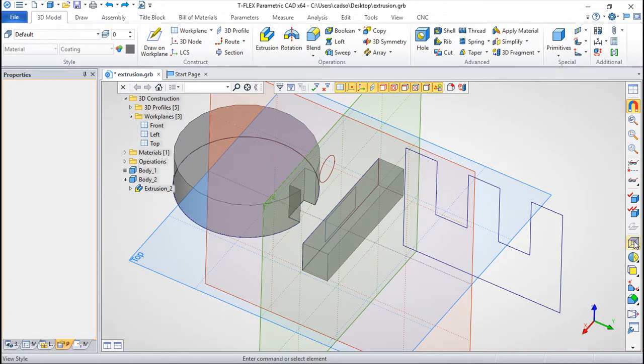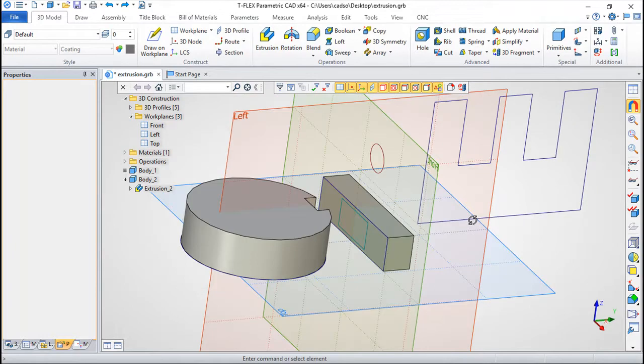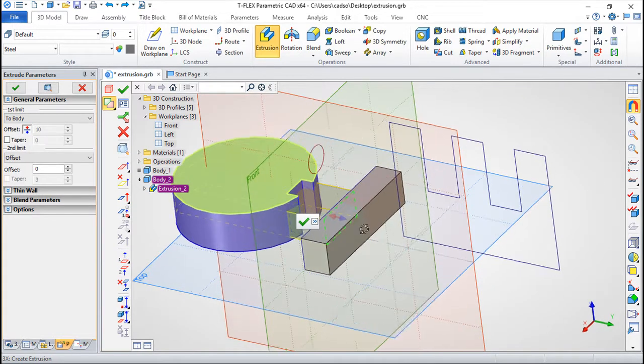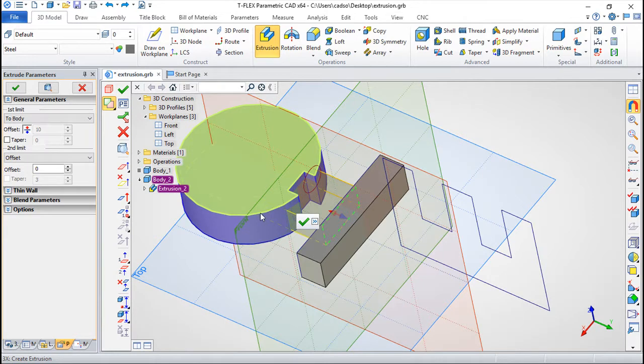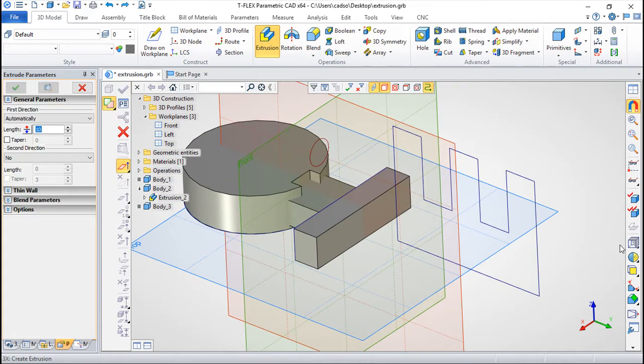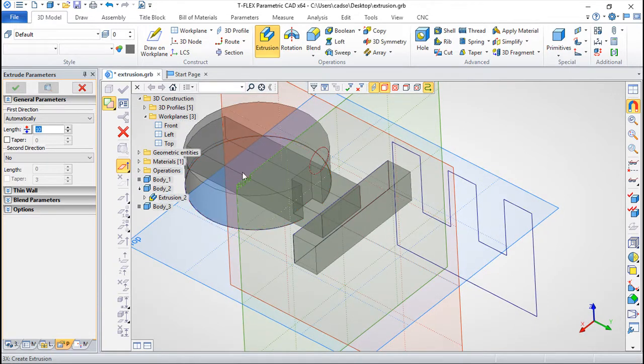I can insert a little more intelligence on this. If I say extrusion, let me take this smart mode out, changing the direction, and for example to body, and in this particular case to body, it will recognize the body, and it will do this a little different, okay? So just say no. And again, showing in wireframe, okay, it put it to the other side.